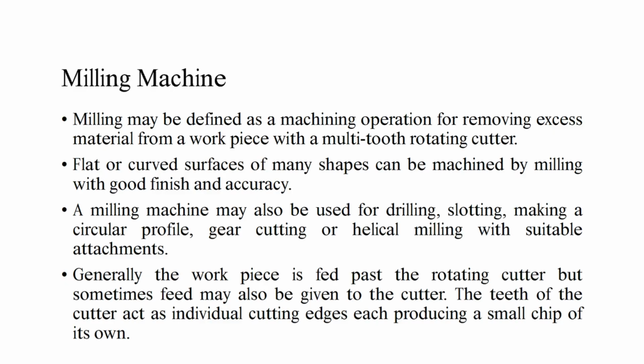A milling machine may also be used for drilling, slotting, making a circular profile, gear cutting or helical milling with suitable attachments. Generally, the workpiece is fed past the rotating cutter, but sometimes feed may also be given to the cutter. The teeth of the cutter act as individual cutting edges, each producing a small chip of its own.